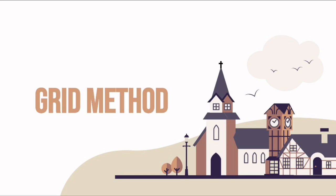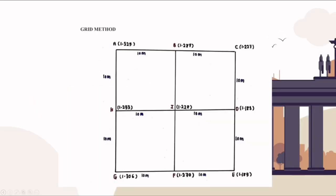Grid method. The grid method of calculation involves drawing a grid onto the plan for the earthwork project. For every node of the grid, we set the value and proposed formation level and calculate the cut or fill required. Once the cut or fill intensity is calculated, multiply it with the depth using the proportion of the grid cell. Do this for every envelope of the grid, then add the volumes together to decide the overall cut and fill volume for the project.